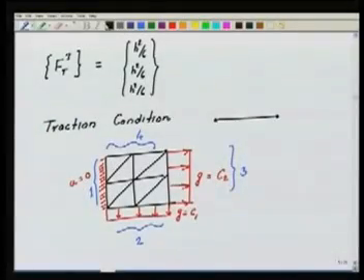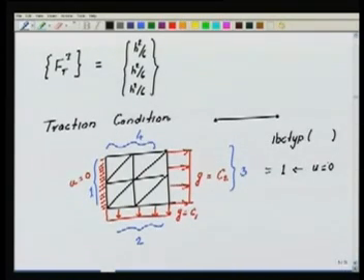So what I am going to now do is, as we had done earlier with respect to the IBC type, remember that we had talked of IBC type associated with the 2 end nodes, telling us what kind of boundary condition is applied on these end nodes. So now the IBC type is going to be defined for the boundary edges. So I have 4, so here I will have 4, and I am going to say this IBC type for a particular edge is equal to 1, this is my choice, when I have homogeneous Dirichlet boundary conditions, that is when u is specified on the edge and u is equal to 0. This is equal to 2 when I have non-homogeneous Dirichlet boundary conditions, that is u is equal to u bar.